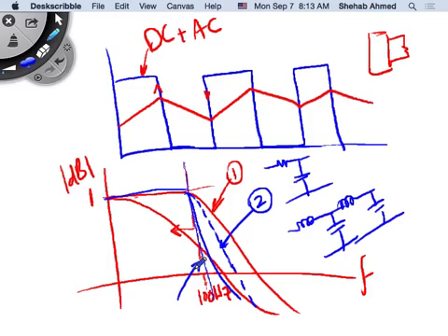But if you have a circuit that is a combination of many L's and C's, then you have to find the equivalent time constant for a circuit like this. And we can make the time constant for a circuit like this a lot quicker, responding a lot faster than these first order filters. And for now, let's think of it that way, and when we talk about filter design later, we will get into more details on that.